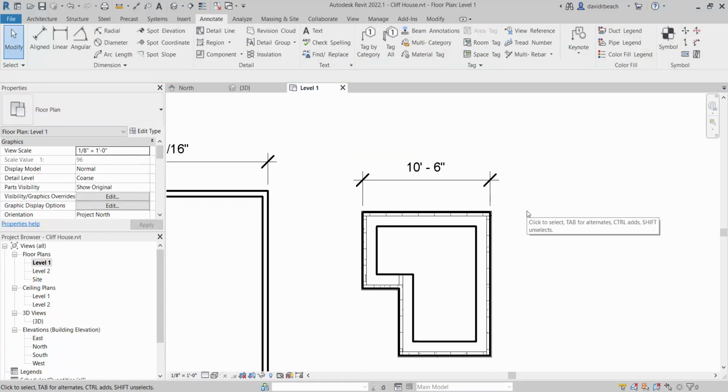But in something like this, what gets built first is the concrete block. And I haven't given the dimensions to the concrete block. I've given the dimensions to the brick that's outside of the concrete block, which, if you're watching construction across the street, is one of the last things built on the exterior.